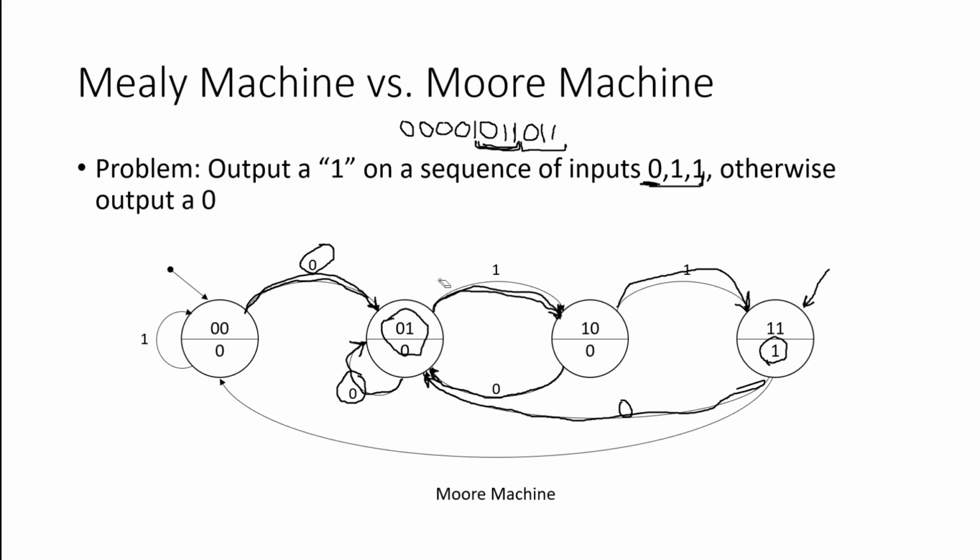We don't know if the next thing is going to be 1, 1. However, assuming that it could potentially be the start of another 0, 1, 1, we have to come back to this state here, which, if I receive that 1, 1, would allow me to come back into state D, or my final state.